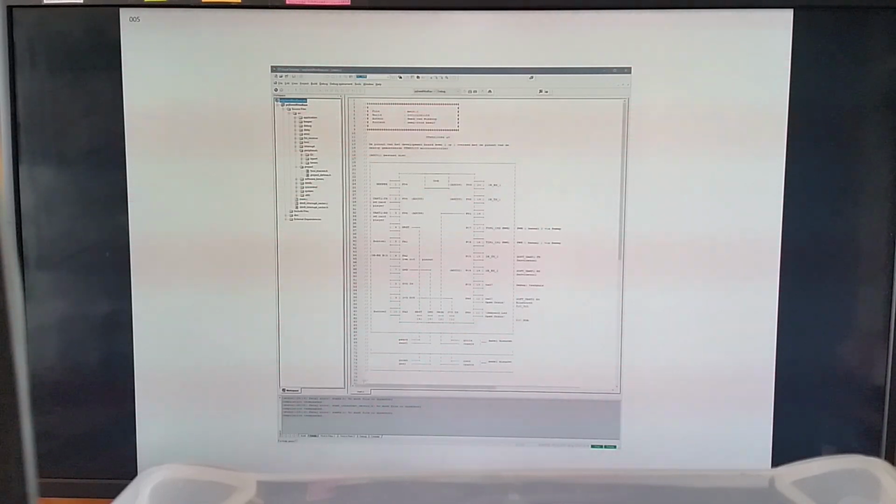Under source files I create my own file, src source, and below that I create all typical modules and also the peripherals. Peripherals are the hardware items that are inside the microcontroller, like an I2C controller, the I/O ports and timers, hardware timers. Then you have the projects folder,